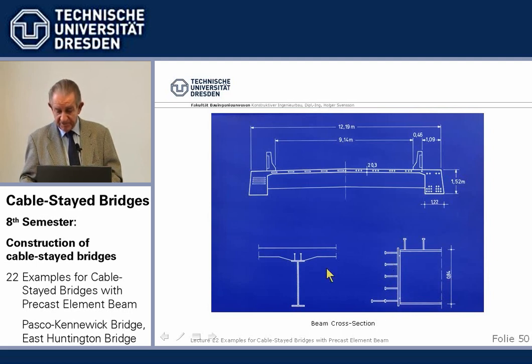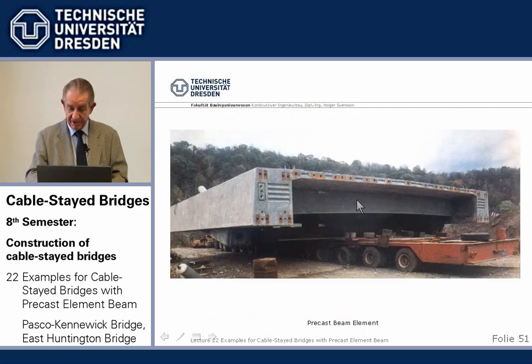Since we have, due to the rotational stiffness, a certain fixing of the cross girder, we have tension here from a positive moment, and in order to carry that we used double stock shear studs, which means we welded on top of one the other shear stud, which permits you rather safely to introduce tensile force via shear studs, whereas normally these only take shear, as the name said.